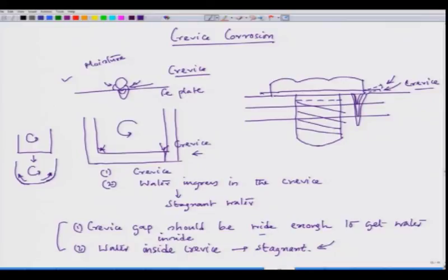corrosion. And in this case, for example, we have to first try that there should not be any crevice. So, one way is we can chop off these particular edges, which will allow this gasket not to protrude out, so that the crevice is avoided. So, this is the design factor we can think of. Now, this crevice corrosion itself is a wide subject. We are just giving a nutshell of what the form of crevice corrosion is.